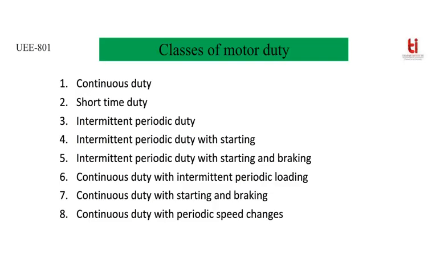Based on that, there are different classes of motor duty, and these classes are continuous duty, short time duty, intermittent periodic duty, intermittent periodic duty with starting, intermittent periodic duty with starting and breaking, continuous duty with intermittent periodic loading, continuous duty with starting and breaking, and continuous duty with periodic speed changes.